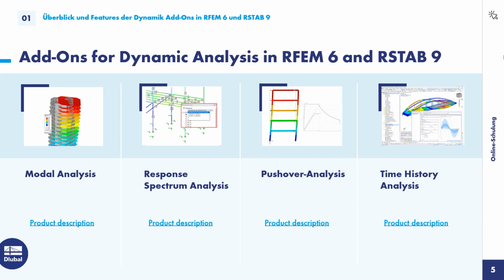The pushover analysis also uses the modal analysis. Basically we consider a structure, and the structure is now being pushed from one side with an increased loading. The distribution of that loading is given according to code.